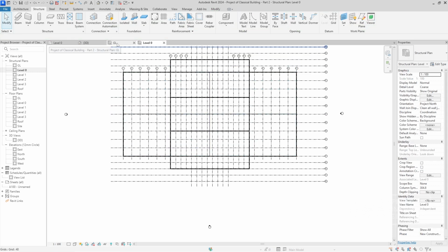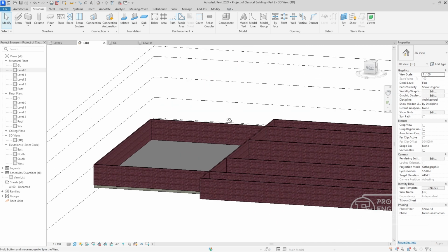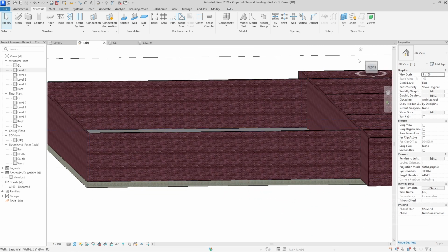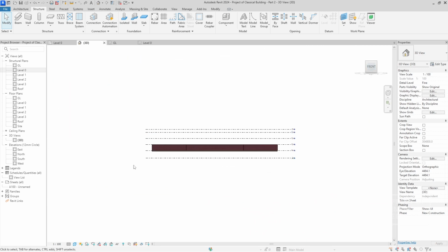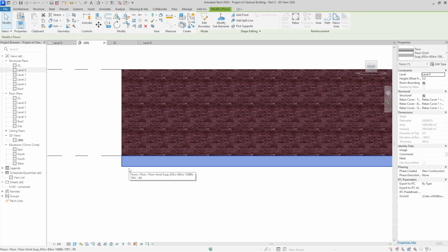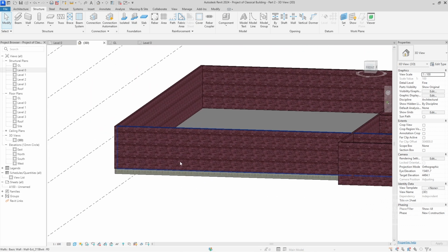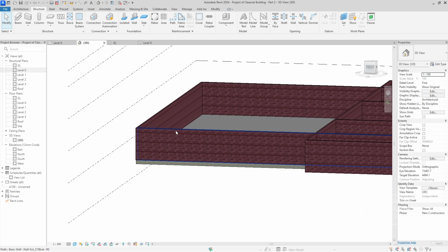So we have a floor here, as you can see. We have a floor of the building, and it is automatically placed from the 0 level downward, and the depth automatically goes to 500 millimeters, as we have set. So after that, let me put in the window.